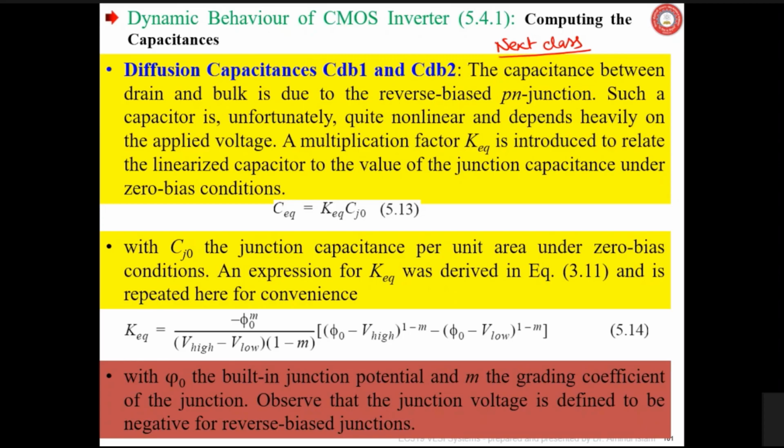And this capacitance is the main parasitic capacitance which has to be reduced if we want to reduce the CL, load capacitance connected at the output node. As such, it is not connected, it is intrinsic capacitance, right? But sometimes we show it explicitly for describing the propagation delay or power consumption, etc., when we describe the inverter. So many times we have discussed, so let me go ahead.